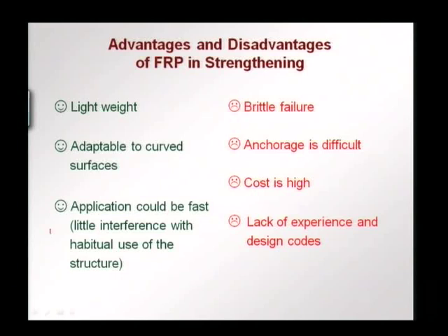Anchorage is difficult, we will talk about it a little bit more in the second part of this lecture. If the FRP is not properly anchored to the concrete surface or any other surface that we are reinforcing, the FRP will peel off, there will be a delamination starting from the ends and we will not be able to exploit completely the strength of the FRP.